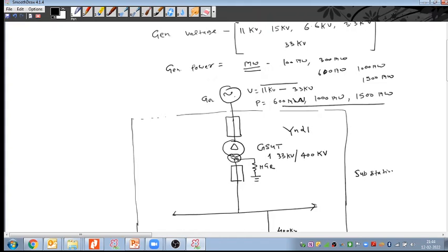So this will be YD1: delta this side, star this side. And now you can ask me why we are taking this. I will explain in the next session, sir, when we have the transformer session. I will explain why we take YD1.